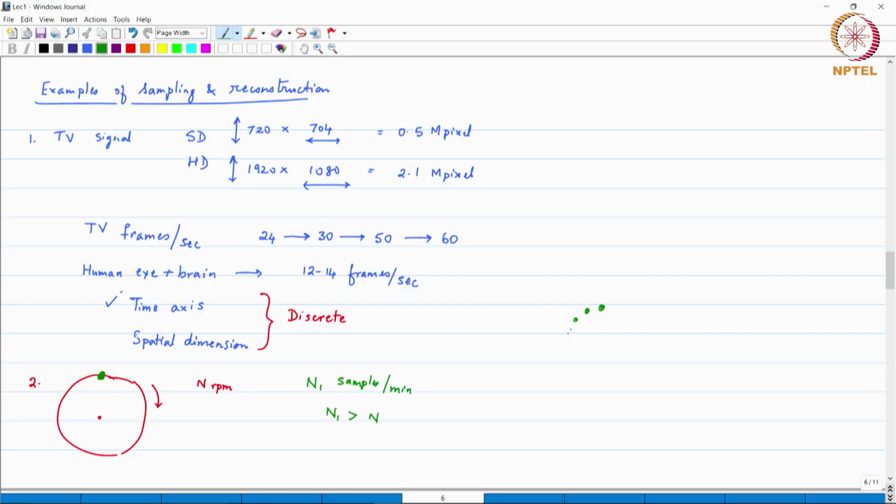More than twice. Basically, it folds back into Nyquist rate. So the minute you violate Nyquist, then there are potential artifacts that we have to be very, very careful with. But it turns out that these artifacts are actually not always harmful. These artifacts in many cases can be exploited. These things come under the topic which we will broadly classify as the effects of aliasing.